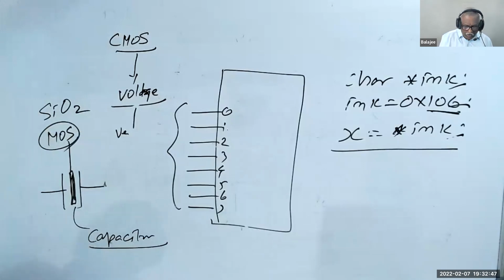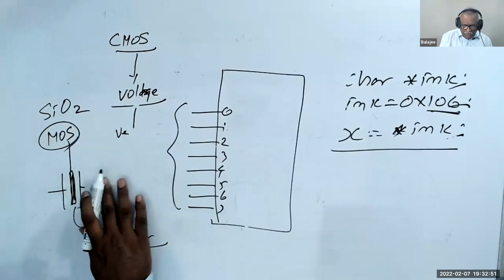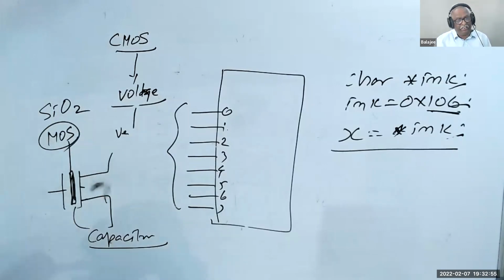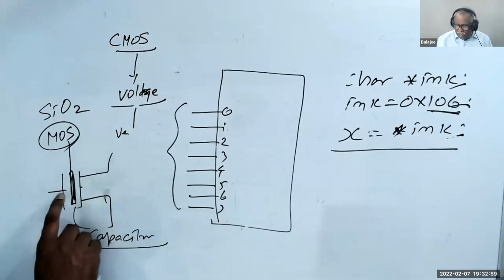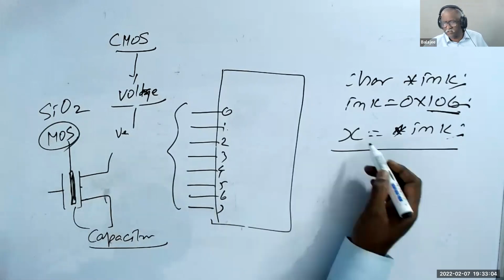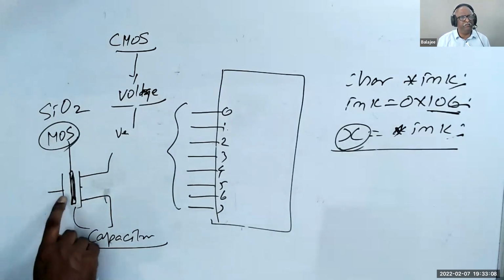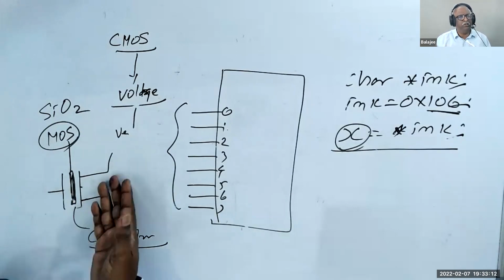So these are CMOS gates, FET. I'm talking about FET, forget about CMOS. Now, when you leave the pin like that and read pin X, very unfortunately, this guy is a capacitor. Whatever voltage that guy will have, it will be the previous voltage.